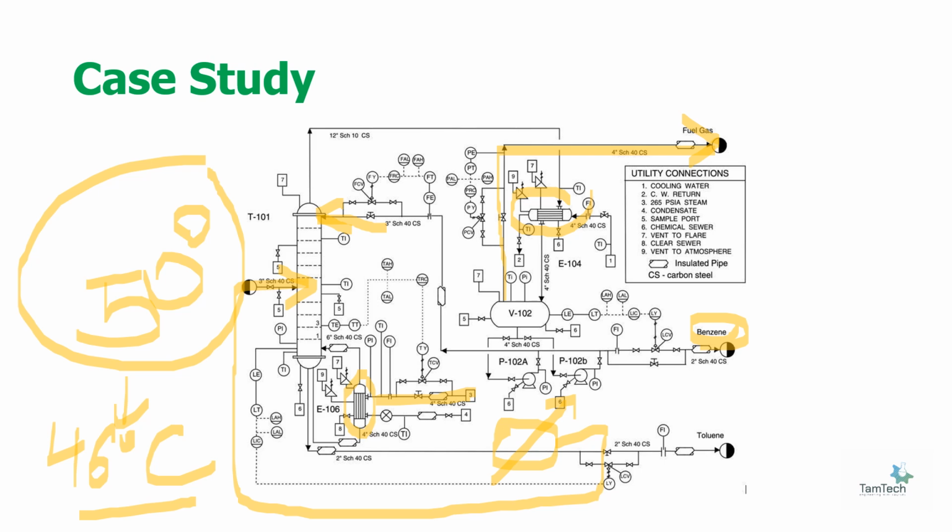It might not necessarily be controlling your pressure and temperature. This is a very rare case, but there might be some exceptions. But always keep in mind that your pressure and temperature definitely affect your separations and distillation principles in the columns. You also need to look at what your controlled variables, manipulated variables, and disturbance variables are. It will definitely help you read the old P&ID and also understand the distillation column unit operations. So actually that's all.